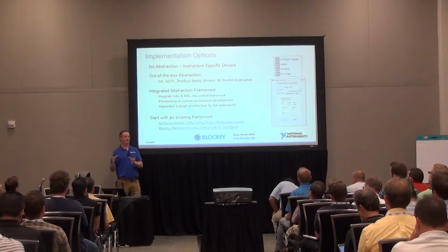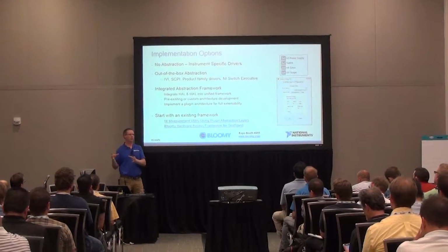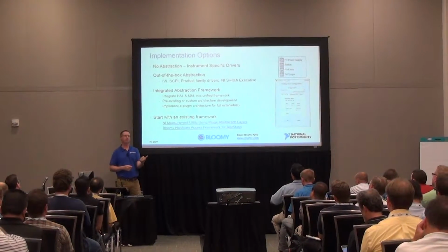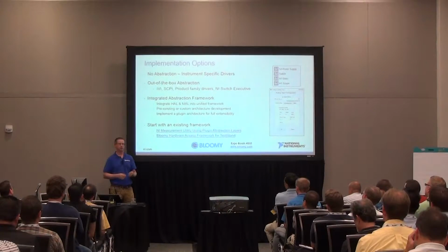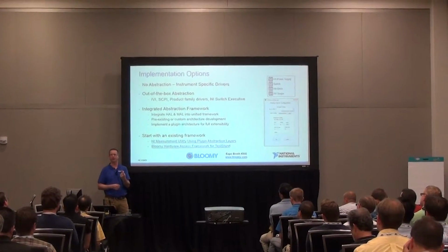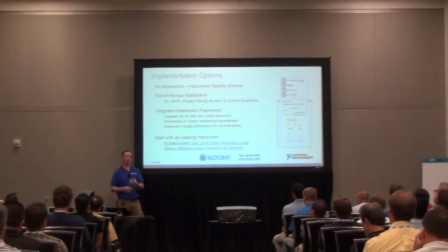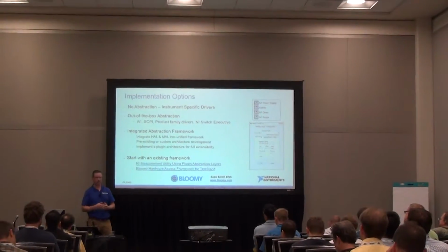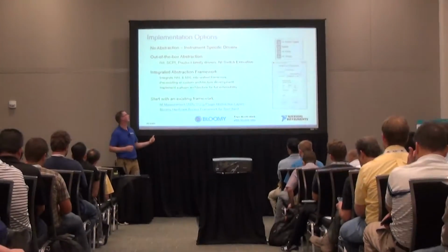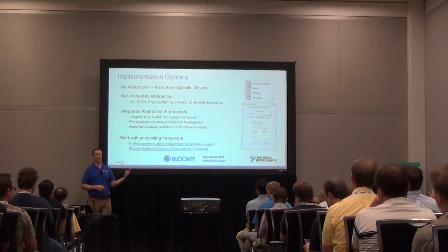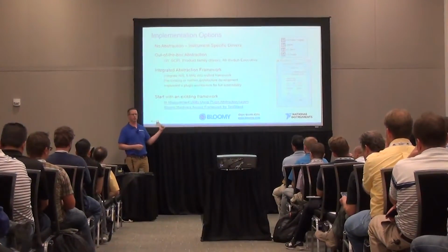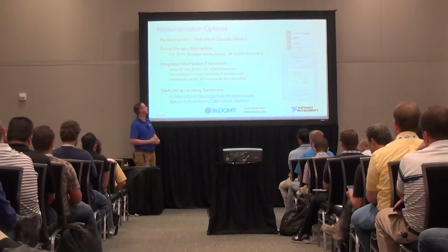If you write an IVI driver, or a driver wrapper around IVI, you now have abstracted to many different, say, power supply vendors. So you wrote one driver, took you maybe a little bit extra work, probably not though, and you can now use multiple power supplies or multiple switches. So there's a lot of out-of-the-box abstraction that's readily available from IVI. SCPI is a command protocol, so IVI kind of supersedes SCPI, so if you implement IVI, you're probably all set.